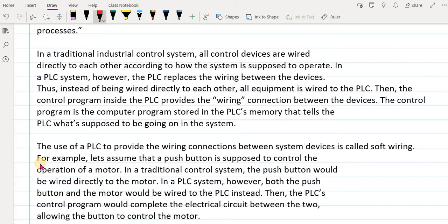For example, it can also provide more safety functions to this motor control, maybe some speed functions or timing functions, how long the motor will remain on. Instead of just connecting the button with the motor to turn it on and off, a PLC will give you much more functionality instead of just turning on and off.